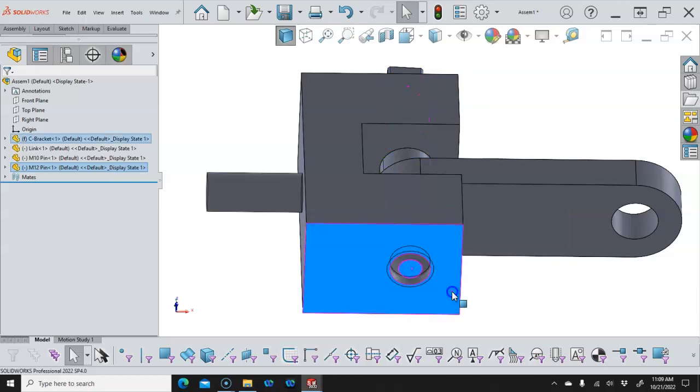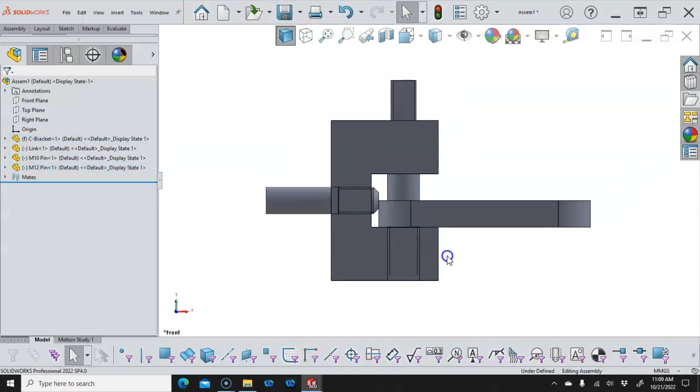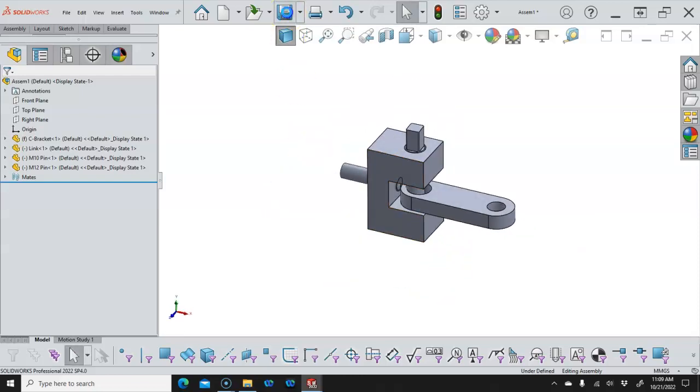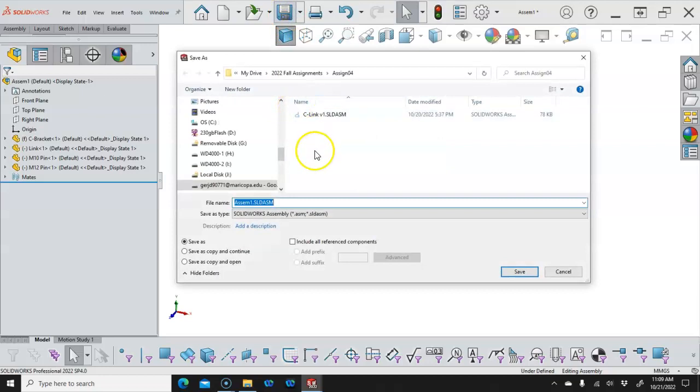So if I were to make those coincident, my concern here is that with the thread length, we might want to shallow that up a little bit so that when this seats, when it goes to the bottom of the threads to that face, there's clearance here. It depends on what's underneath this, that we don't really want this to act like a jack and start lifting up the part. All right, so we'll go ahead and save this.